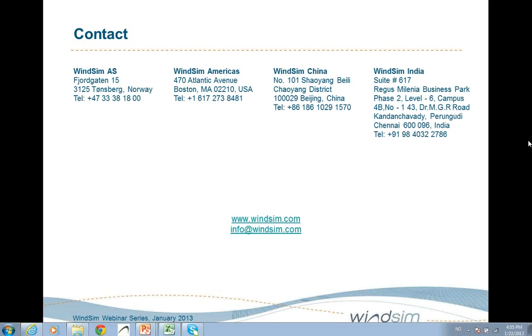Then the next question is if there's any recommended standardized minimum resolution for the analysis. Of course, there is no standard, but we normally recommend that a good CFD study should be run at least at 25 meter resolution to ensure that you capture all the important effects. If you are in really complex terrain and you know that you could have recirculation, then it's sometimes even worthwhile to have a better resolution, as long as your terrain data also has a good resolution to capture the effects.